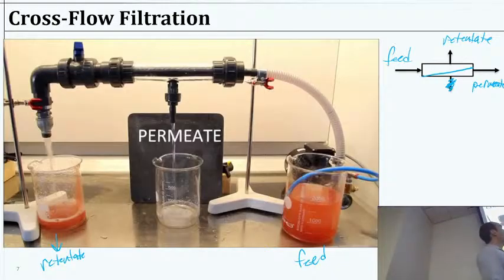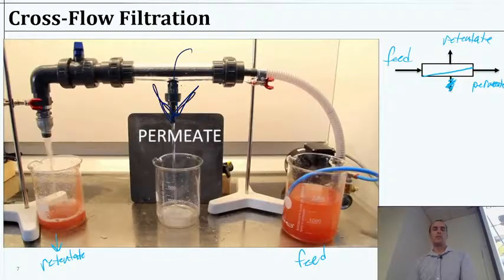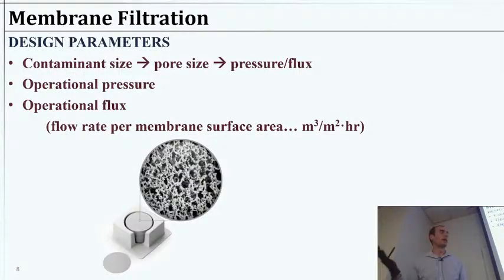In this case, it kind of looks like you could have the permeate going across to the other side, but in fact, it's going across through this cylindrical membrane here and being collected out the bottom. So the shape of the membrane apparatus might be a little tricky sometimes, but I'm just showing you that we can operate them in some way that makes sense.